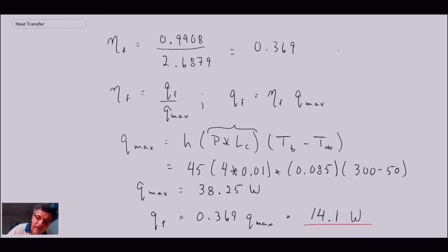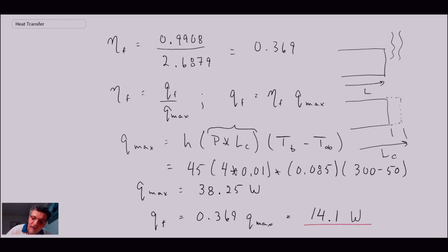And if you recall what I said last time in the last segment, typically our case 2 solution would have free convection from the end. What we're doing here is we're taking that length and adding on another corrected length, giving us our corrected length over the normal length, and it is assuming that this tip is then insulated, so there's no heat transfer there.